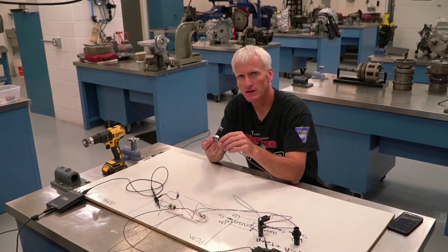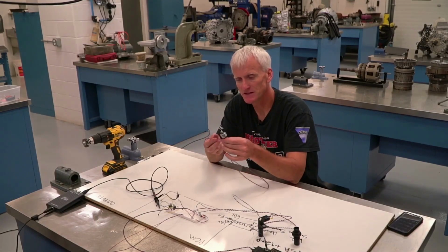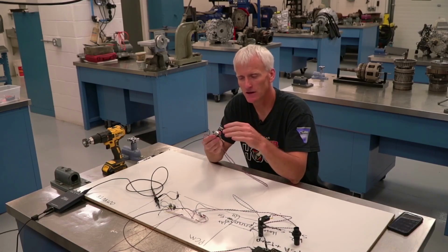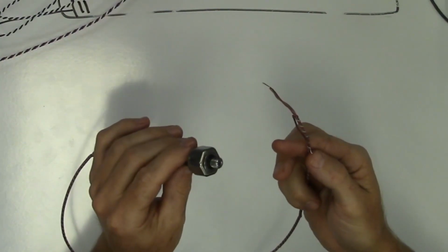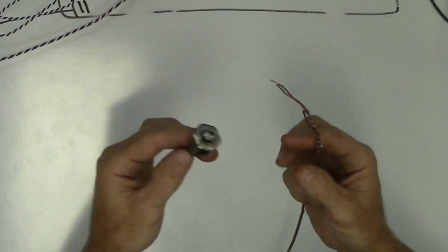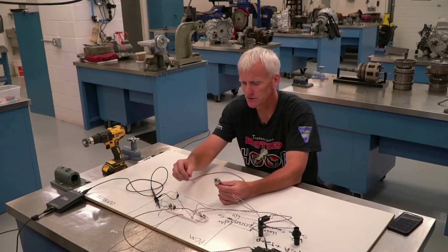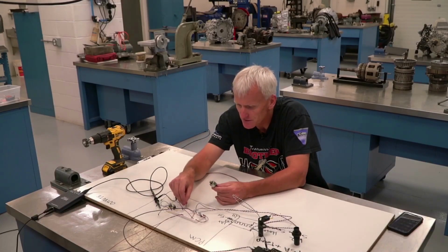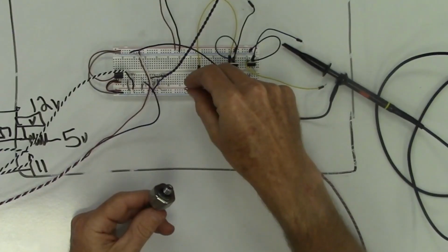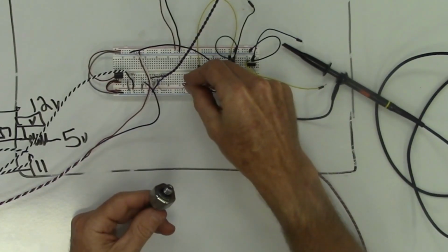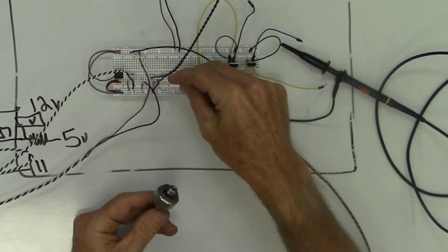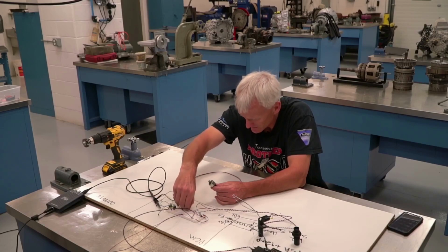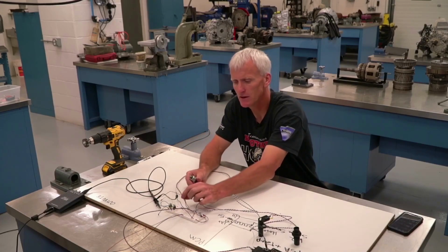This is different. This isn't a pressure switch like we saw first. This is a sensor, so it's going to vary its output based off of how much pressure the transmission produces. And in this case, it's used on a Jatco, and it's a primary or secondary variator pressure. So this thing's designed to read probably up to 1,000 psi or so. But it's going to receive 5 volts and ground. So it's a 3-wire device, so it receives power and ground. And then that third wire is just going to basically be the sensor input.